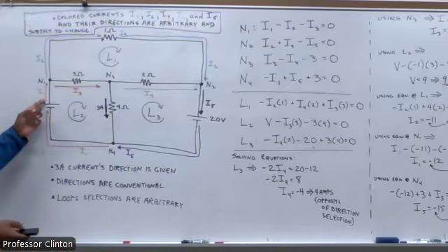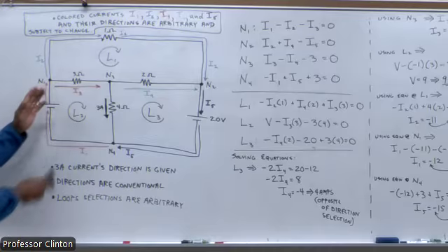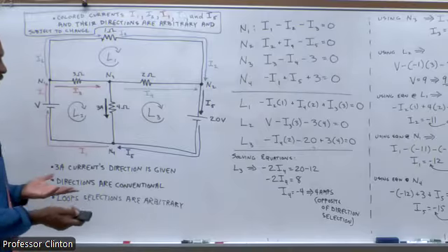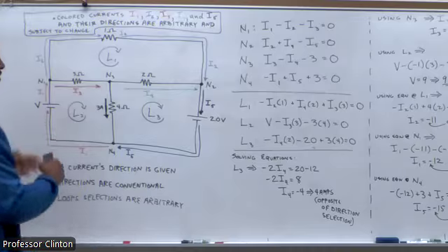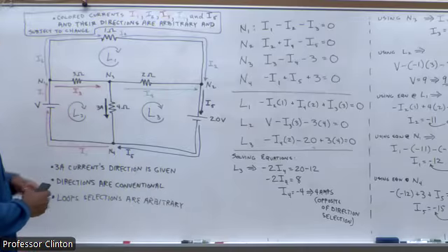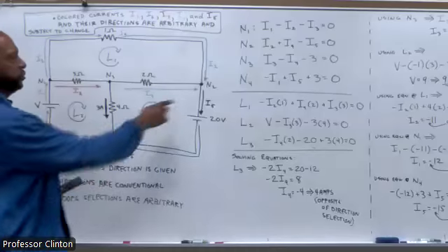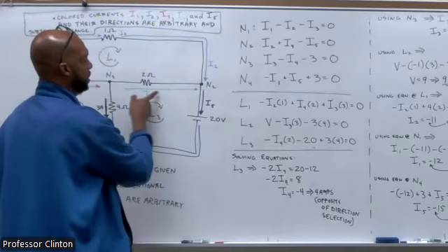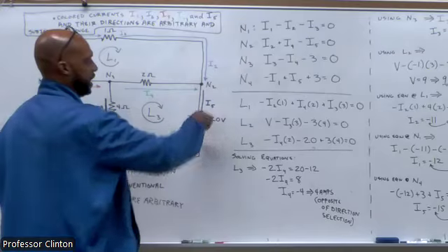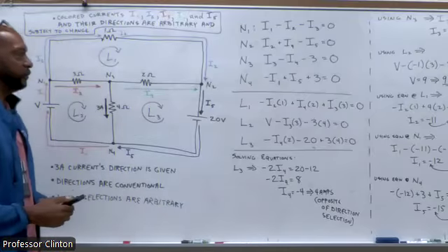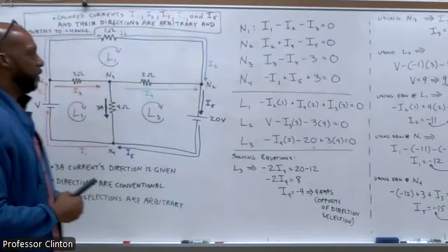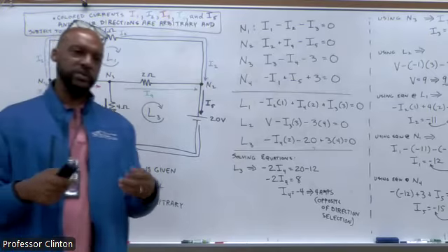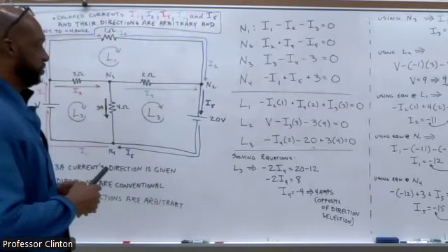So we're assuming here that current 1 flows into this node, thus the other 2 will be the additive inverse of I1, since the net flow should be 0. Likewise for node 2, you can see I2 is an input, I4 is an input, and I5 is extracting, if you will. And I go through that for all 4 of those. Again, keeping in mind that the directions of the currents are arbitrary, so they're subject to change.